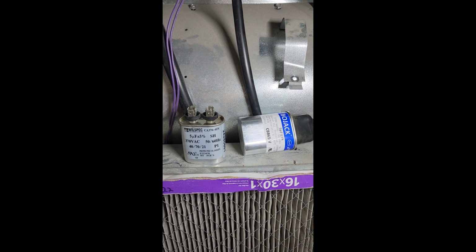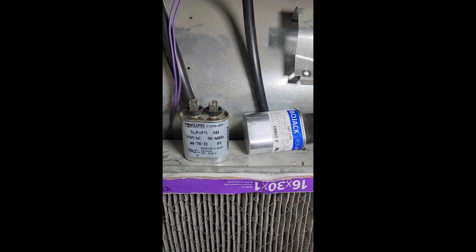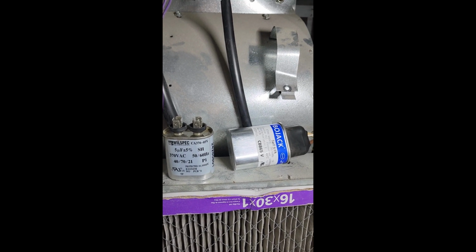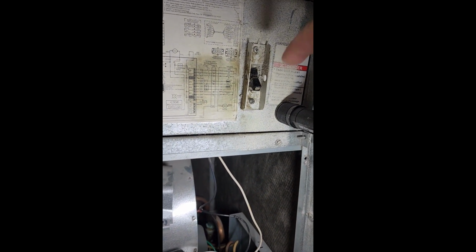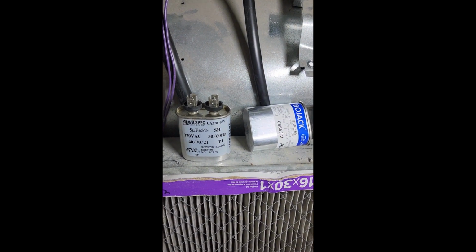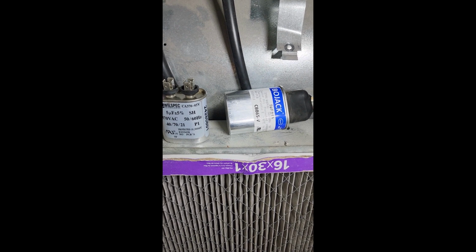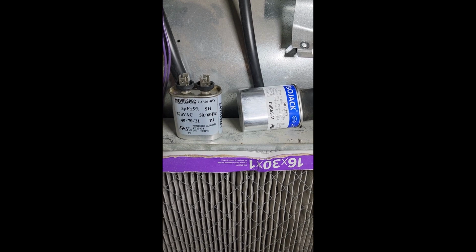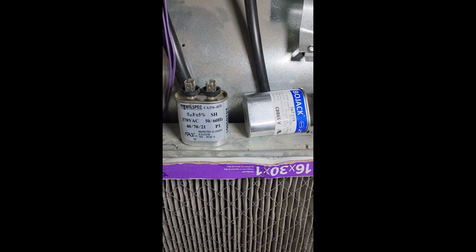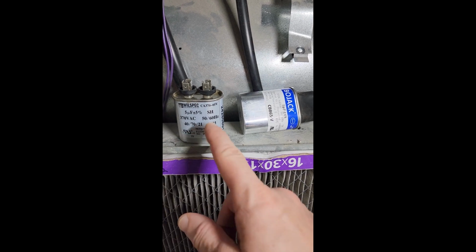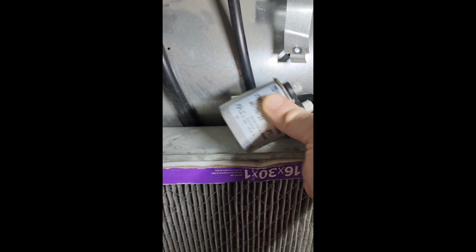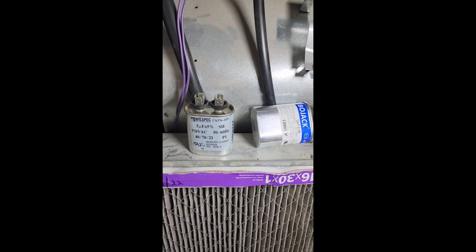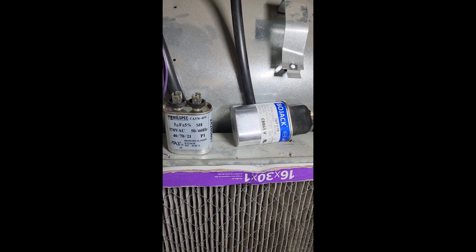Alright, so we have our new capacitor all hooked up, and before we do our final test here, where we're going to have the main panel breaker back on, just need to energize this switch here, but I just wanted to point out something about the capacitor itself. So when I was looking for the replacement, I saw that there are a whole bunch of different types of these capacitors. And clearly this is a different brand. It's even slightly a different size. But the most important things are the shape, so it fits into the bracket properly, and of course the value.